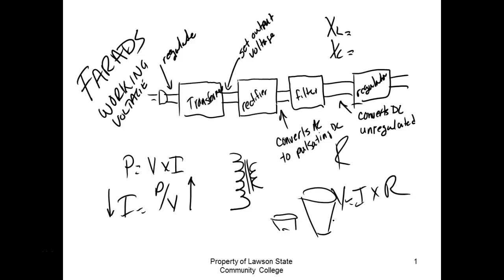And of course, the formula to figure the charging time is time equals R times C. That's how much resistance you put in series with it. But this is actually 63% because it charges at an exponential rate. The rule of thumb is fully charged is 5 times R times C. And if you did all the math, that's around 99%, which to us is good enough, right?